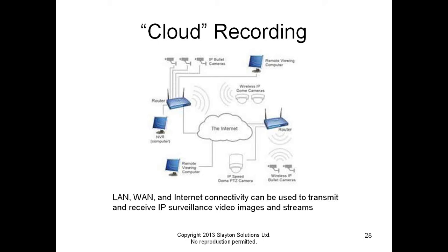The second thing is that when we do the recording remotely, or cloud recording, we reduce the cost of the initial system because we eliminate the NVR or DVR that we would otherwise sell the customer. If we don't have to supply an NVR or DVR, hey, system costs less money. And in this business, less money is good.